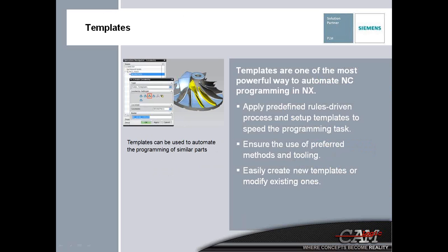The next action item that we're going to talk about today is templates inside of NXCAM. Templates are one of the more powerful ways to automate NC programming, and one of the most often used ways that our customer base uses NXCAM to automate NC programming. You can apply predefined rules in a driven process and set up templates to speed up the programming task, ensure the use of preferred methods and tooling, and easily create new templates or modify existing ones.